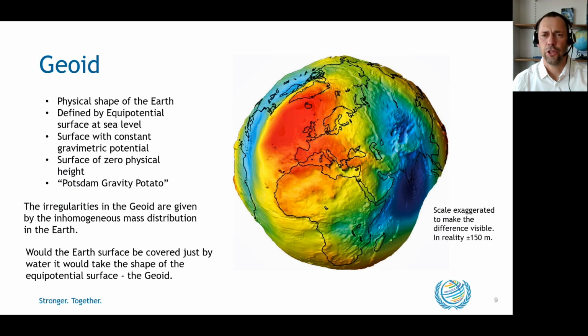Easily explained, the geoid is a form of the Earth that the Earth would take if it would be completely covered by water. As you know, the water, following the gravitational force, flows always downwards. Now imagine the Earth is covered just by ocean. There are no continents. Then the Earth would take the shape of a geoid, like shown in the picture. The water equilibrium will not give a perfect geometric body. There will be differences in height in respect to the geometry.